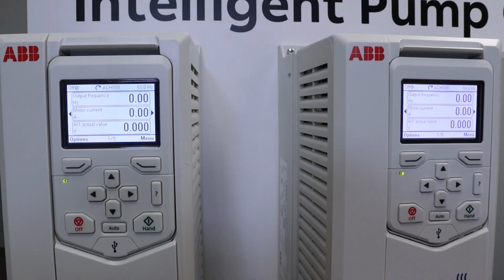At this time, we're going to look at setting up intelligent pump control. Each individual drive has been set up for its individual motors and motor parameters and any special parameters needed for the pump or fan that individual drive will be controlling. Now, to set up intelligent pump control is easy, and we're going to use what we call the inverter-inverter link to move parameters around. But first, we have to set up each individual drive.